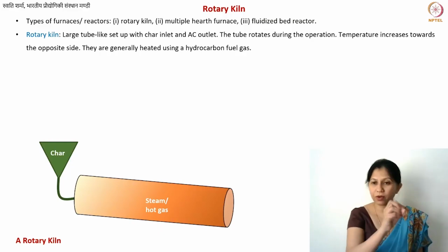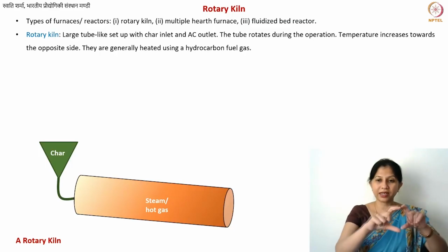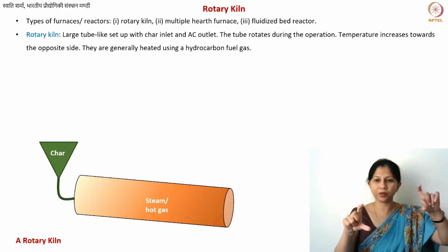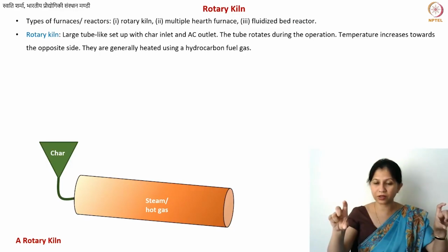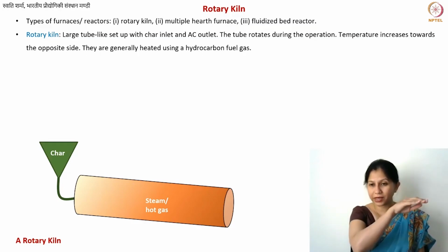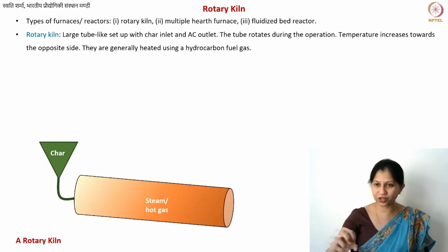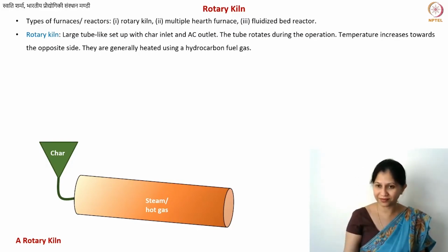And now we put them in our tube. One thing you will notice in this tube is that it's an inclined tube. It's not a perfectly horizontal tube. It's slightly inclined, and there's a reason for it. If the tube is inclined, then the material can move along. Due to gravity, it will just move forwards.